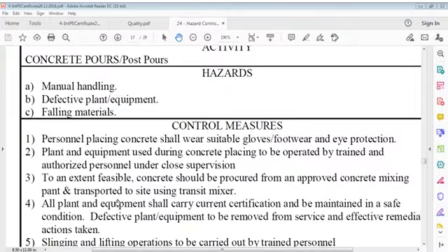On slabs also, all sides of slabs, suspended slabs we usually call them. Slabs and beams are called slab pour. The slab portion and beam portion, generally along with small necks of columns, are poured at the same time, monolithically, and that is a very serious pour, quantity-wise, quality-wise and safety-wise.